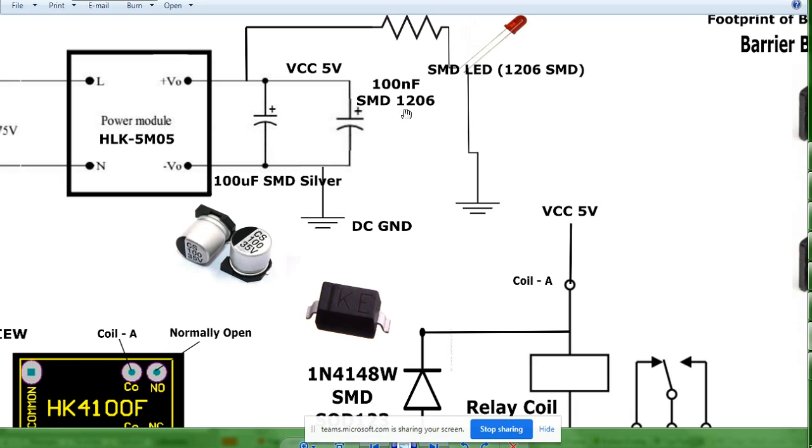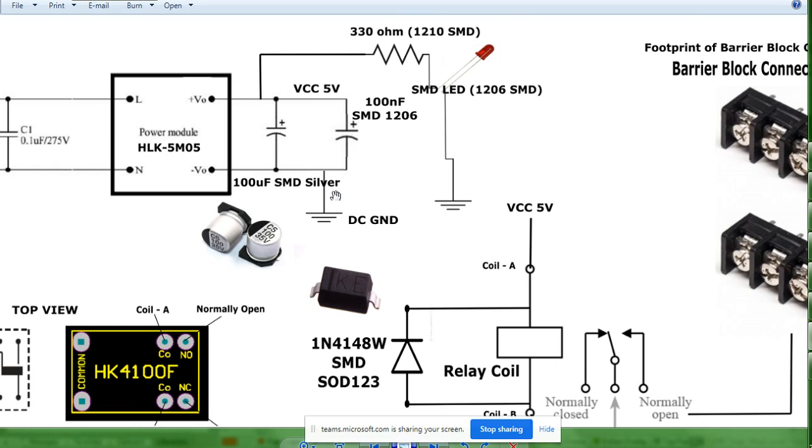We will talk about that one, but let me just confirm before that that you have an idea about capacitive reactance. Then I can tell you. But in any of the circuits in your whole 4 years, you are always going to see on the power supply two capacitors, one very big and the other one very small, so that this will take the large disturbances, and this will take the small disturbances in the voltage over there.